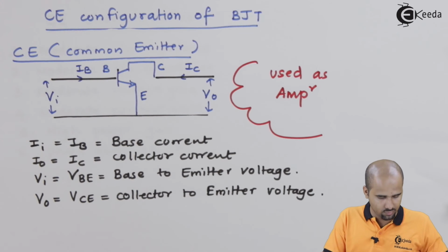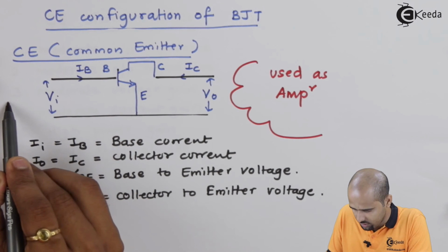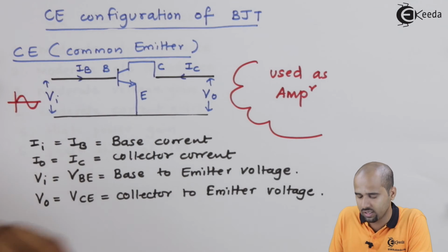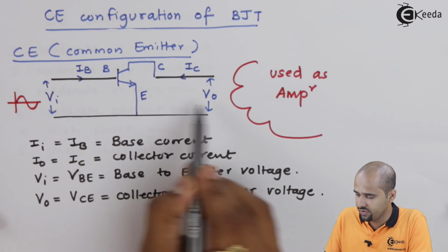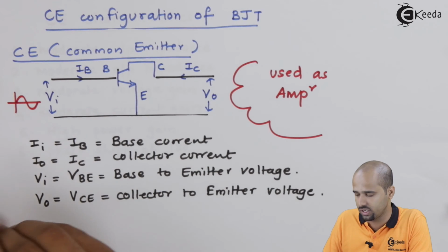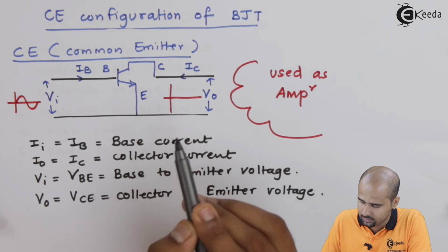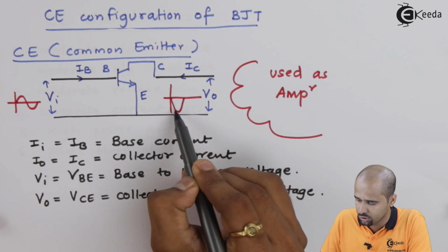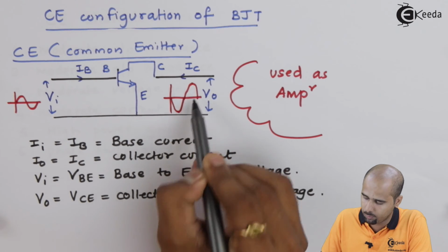See this circuit where we are giving input as an AC signal, where the first half cycle is positive and the second half cycle is negative, whereas whenever we amplify a particular input signal, at the output stage we will be getting the phase shift in the form of 180 degrees, where your first half cycle will be negative and the other half cycle will be positive.